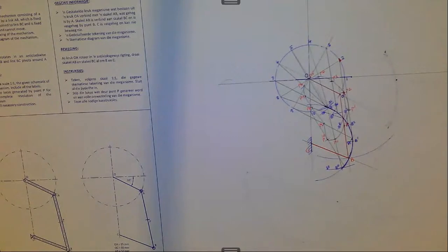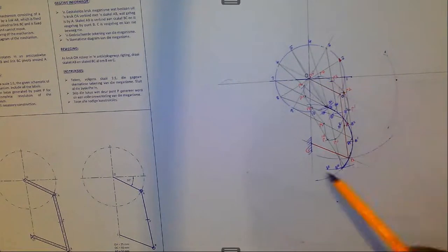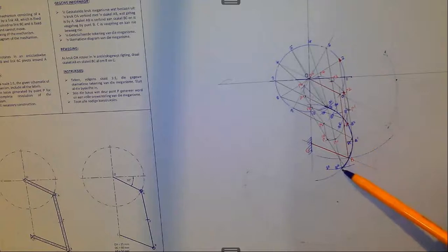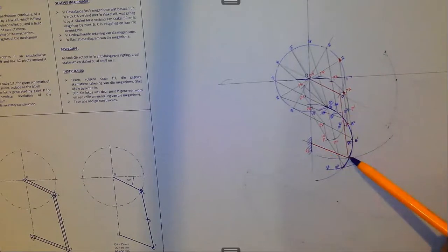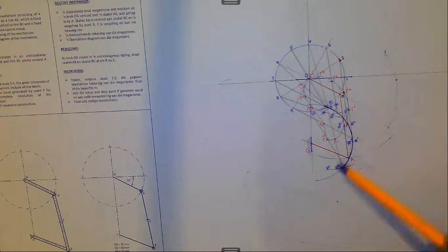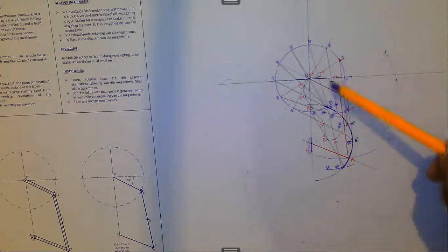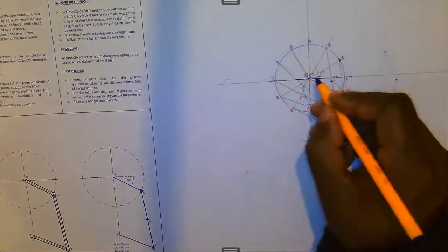So that is the path that is followed by point P, right? As the crank revolves about point O, right, with this part not moving, right? Remember, point B can only move along this arc, right? We cannot stretch this one, so it can only swing, right? As point B swings like that, it would push, right? Point P there, right? So we can outline this now.